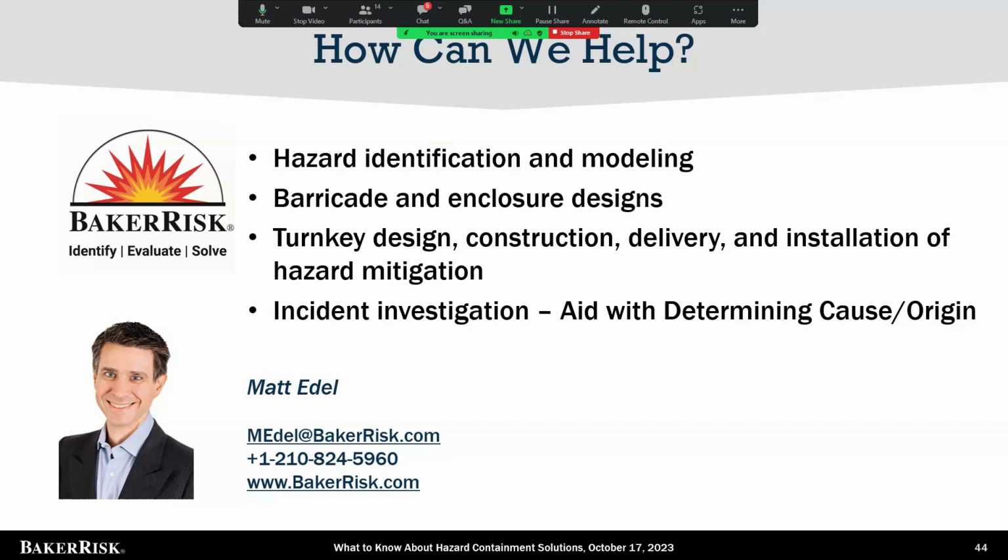Sometimes the tubing that goes from the pump to the item under pressure might be exposed out in the open. You can do something like put a tether to it or put intermittent anchors to secure it to the floor or the wall so that you wouldn't get hose whipping or other types of hazards introduced.